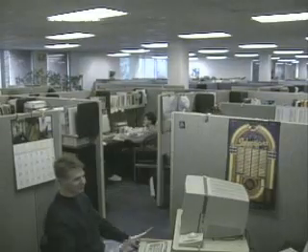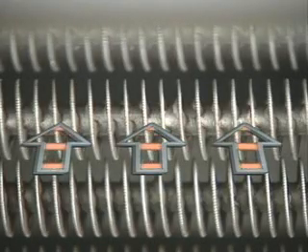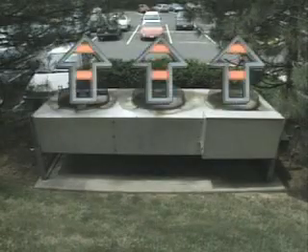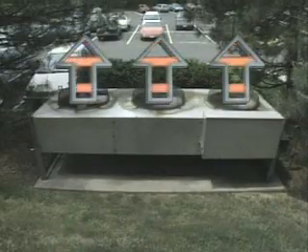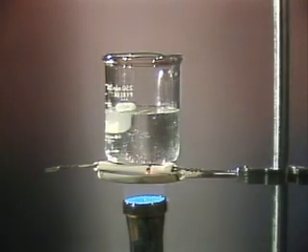In a refrigeration system, heat is transferred from a substance that is being cooled into a refrigerant. The refrigerant carries the heat through the refrigeration system and then transfers the heat to a substance that is able to absorb the heat. When heat transfers to or from a substance, a couple of things may happen. The temperature of the substance may change, and/or the substance may change its state. In general, matter can exist in three states or phases. It can exist as a solid, a liquid, or a gas. When a substance changes its state, the change is called a phase change.